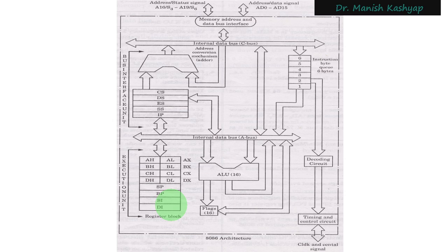But at this point, all I can say is you should have this general information that C register is usually used as counter. It is by default used as counter with some very specific commands. And we will see that when we do programming, that C register is by default used as counter register. Right. Similarly, A is the accumulator, and then these registers also have special purposes: source index, destination index. So when the time comes, we will come to know what their special purposes are.